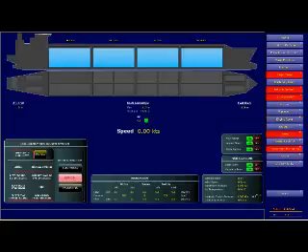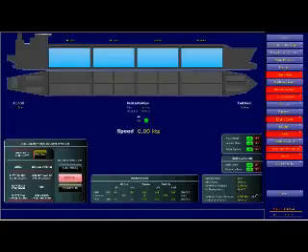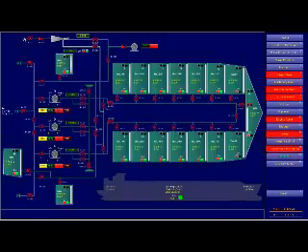So technically, our status at the moment with the shore is that we have, of course, no flow because we haven't started our pumps. All our parameters of ventilation and other alarms are okay. The only alarm we are getting here is the ballast system. There is a low level alarm because we were doing certain ballast management.